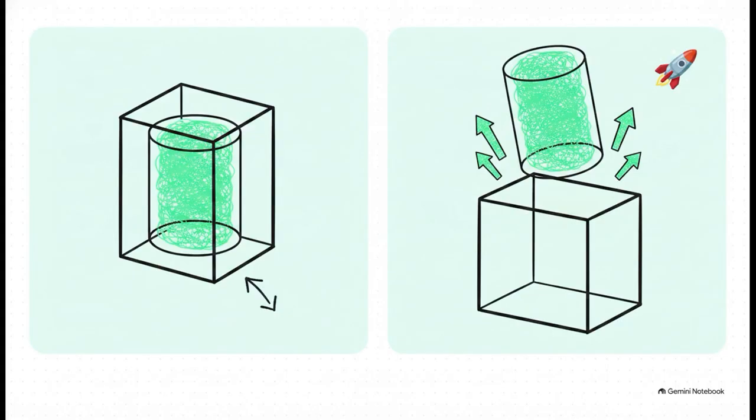You can really see the difference when you map it out. Without the modifier, a standard position tolerance zone is basically just a cylinder trapped inside the chunk of metal. But with that projected modifier applied, that cylindrical tolerance zone suddenly floats up into the functional space above the part. By using this, we are essentially telling manufacturing and inspection, hey, I don't actually care where the hole is inside the block. I only care where the fastener ends up in the air. We completely shift our control to the functional space where the mating part will actually sit.